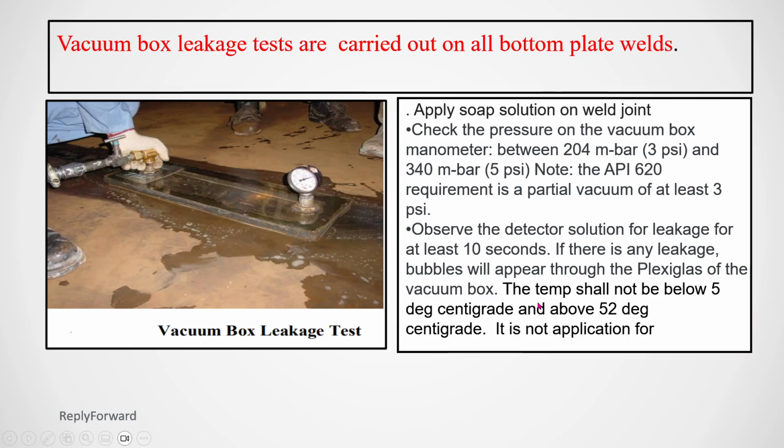But this test is only applicable between 5 degrees centigrade and 52 degrees centigrade. Otherwise, the soap solution will not work and no foaming will be there. So that is only possible for temperatures between 5 and 52 degrees centigrade.